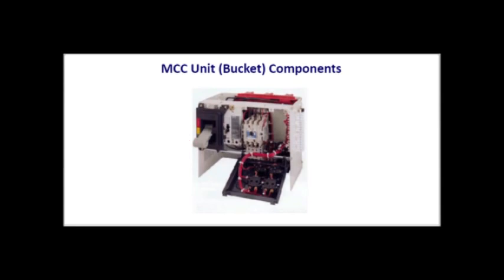There's the motor starter itself. There are the pilot devices such as the start-stop push button, selector switch, and indicating lights. Terminal blocks are usually mounted on the side of the bucket.